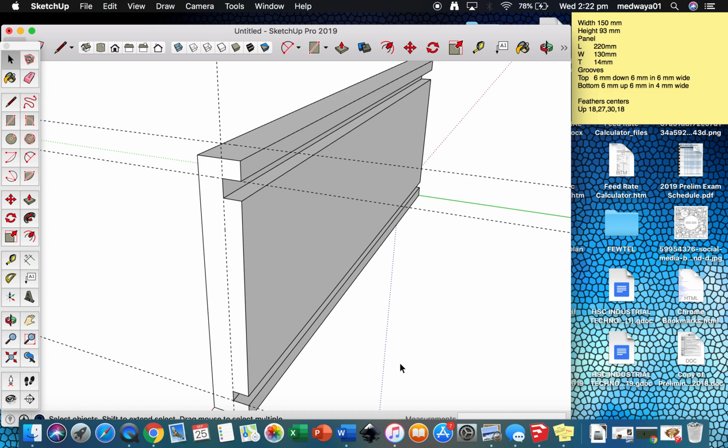So the first thing I did was draw an object which is 45 degrees across from there and represents a solid object intersecting where I want to split this object. So I'll read that again. Line, click there, there, that corner. Notice these little coloured dots and squares. They're telling you that you've reached a point, an end point of an intersection or a line or an object. They define where these objects are. They're called reference points. We've drawn the triangle.